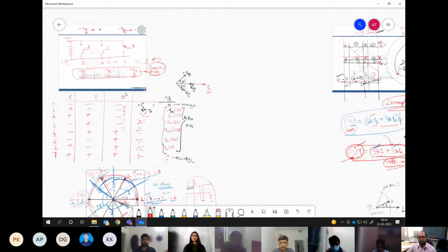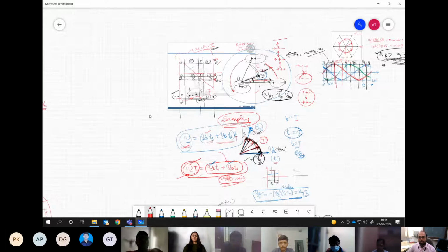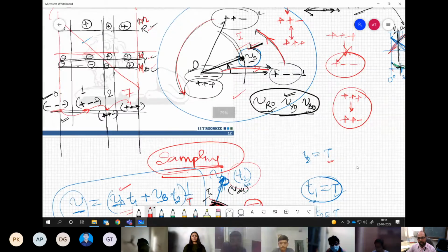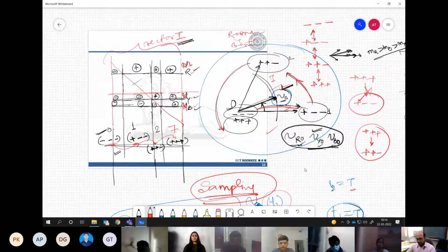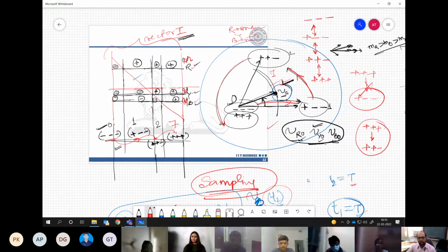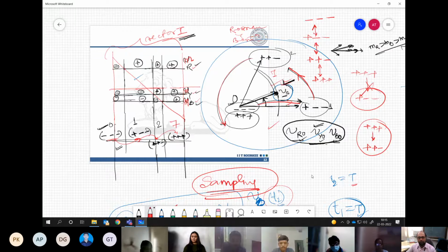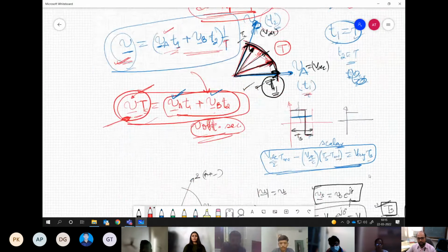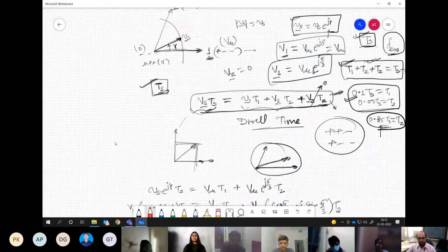First we have seen that any other PWM technique, for example 6-step or sine triangle, is also basically applying one of these active vectors or 0 vectors somehow, that's the option, to realize the average value of the voltage, whether in terms of per phase or in terms of the voltage vector. But effectively the point is that some voltage vector is applied at any given point.